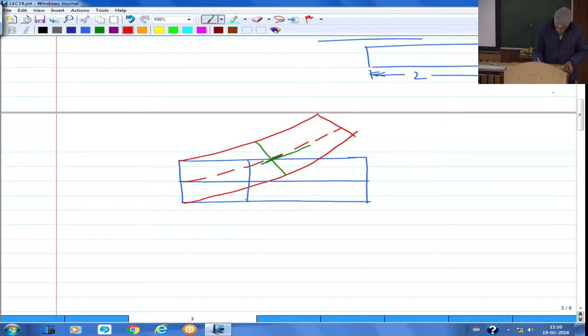The actual normal, that means initially we draw this line in the undeformed configuration. That line goes to this particular configuration here. This is actually a straight line, although it comes out as a curve the way I have drawn it. So the blue line goes here, whereas the green one is the normal to the tangent drawn to the middle surface or the neutral surface at this location.